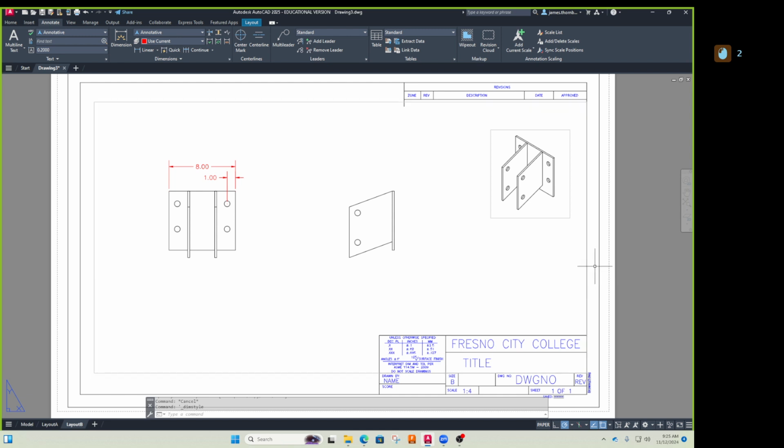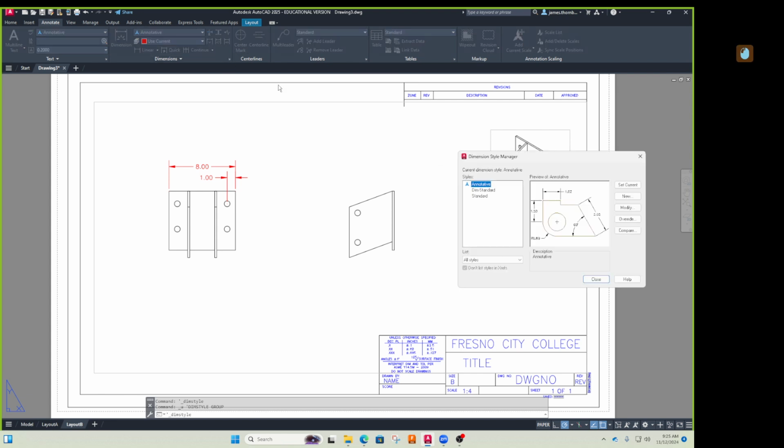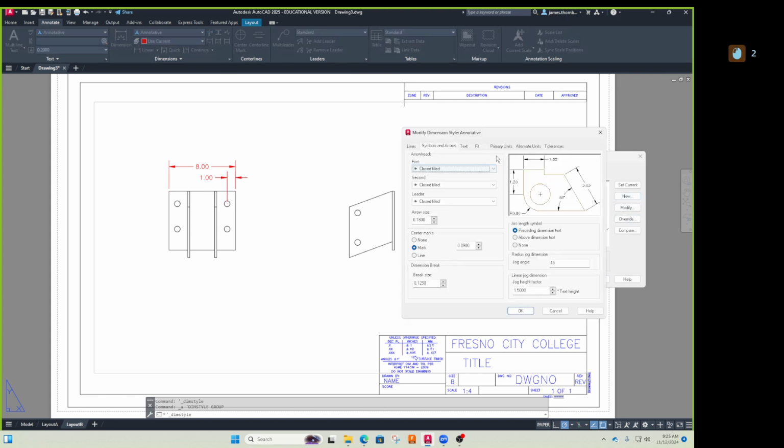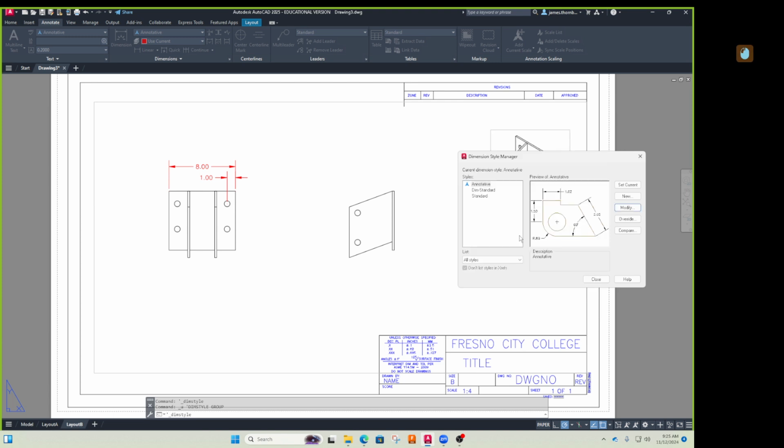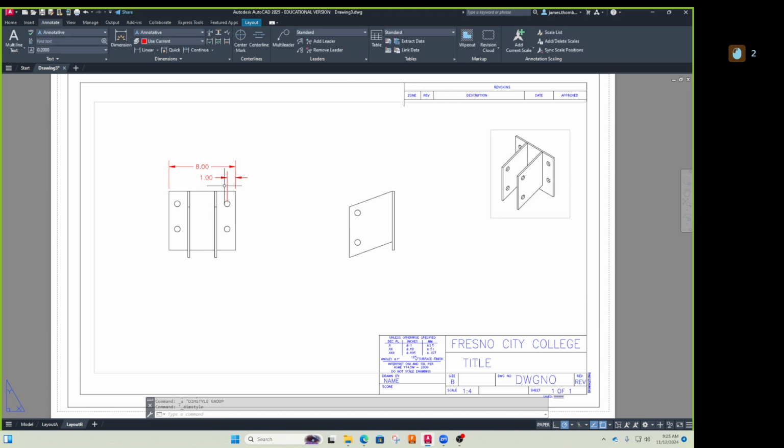That's okay too, but 0.18 is what it should be. But a lot of people make it a little smaller just to make it take up less space. And then the units. So the primary units, just change it to 2 places, and turn off that leading 0. I think I told you to do that on the template. That way, if we have smaller ones, it's not there.